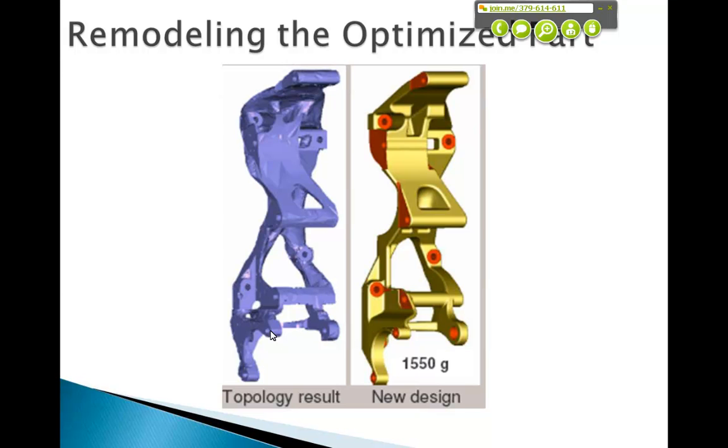from using topology optimization is that, if you remember, the original design space for this bracket was just a big block, and you would not initially be able to know in your mind where the load paths are going to go through that block until you have it do a topology optimization.